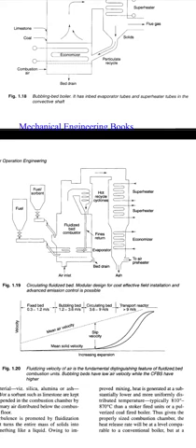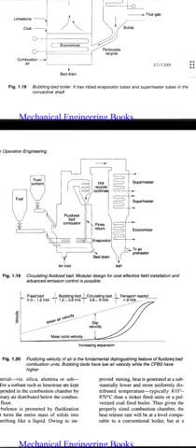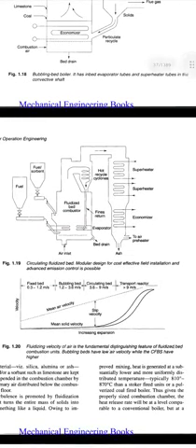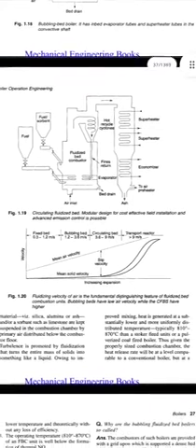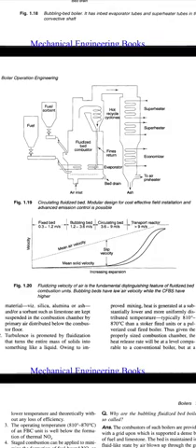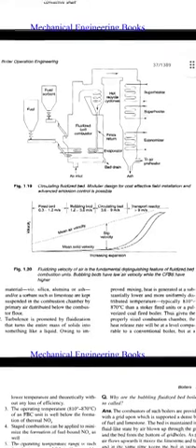Fines return is available. So the flue gas is going through the combustor and hot recycle cyclones. After the hot recycle cyclones, the fines return. The flue gas is going to the right side of the column, which provides the first stage superheater and second stage superheater, then economizer, then it is going to the air preheater, and the ash is collected through the right side of the column.